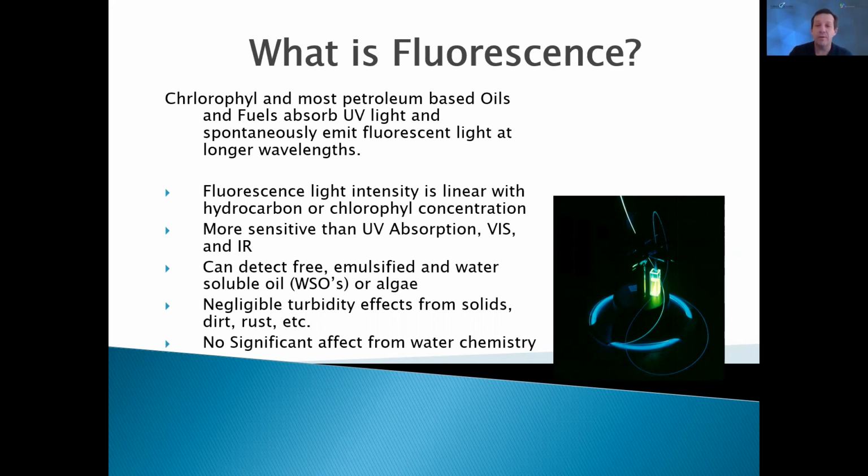Water is exposed to that light source. Any oil that's present in that will absorb some of the light, and will spontaneously emit a different wavelength or a different color of light. So this response is instantaneous. It is a nanosecond response, and it is continuous. So we have the ability to make these things for sample analyzers, so you can do a manual measurement, but most of them are continuous online instruments. The light stays on continuously, water flows through the devices continuously, and we make a light measurement continuously.